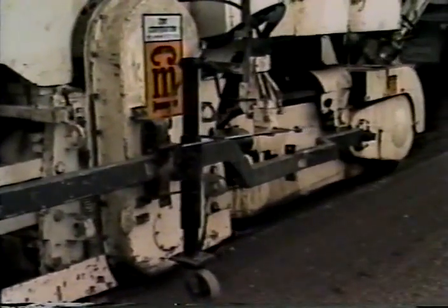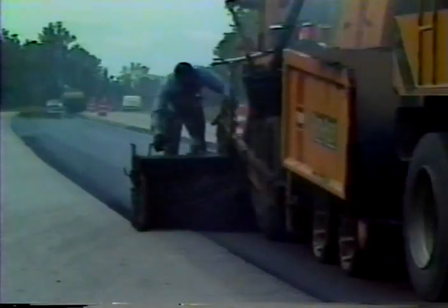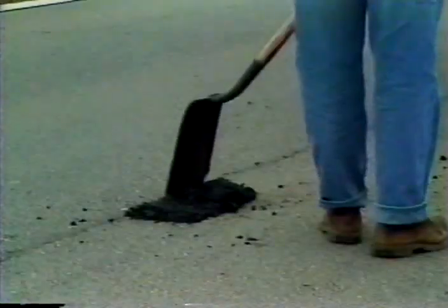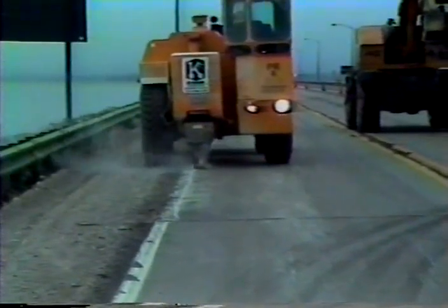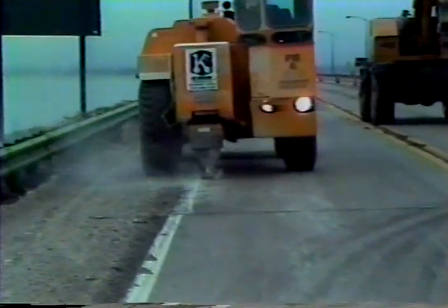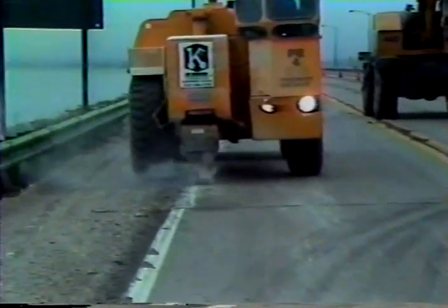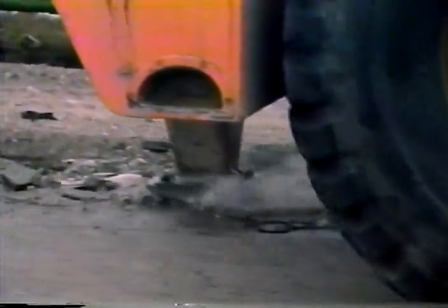On bituminous pavements, severe surface distortion should be milled off or leveled by placing a leveling course. Potholes should be filled, and areas of badly failed base should be removed and replaced. In lieu of pre-overlay repairs, cracking and seating or rubbleizing may be used on concrete pavements to provide uniform support for the overlay. On severely deteriorated pavements with major structural problems, these techniques may be more effective than pre-overlay repairs.